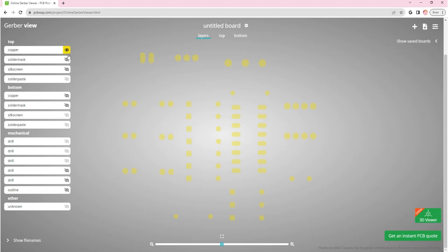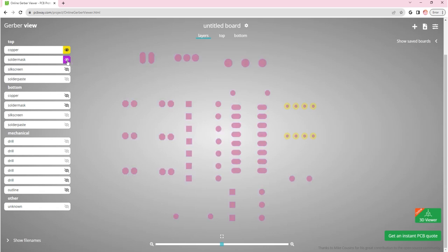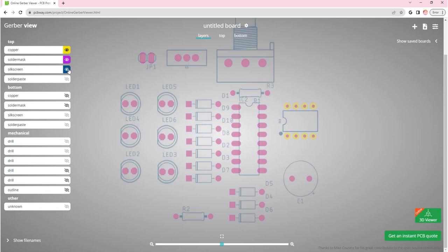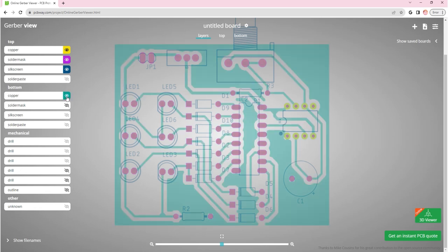The PCB manufacturer requires specific information pertaining to each step in the manufacturing process of your board. This special information is described in files containing plot and/or drilling information. For example, one file for each signal layer, for the silk screen, for the solder stop mask, the cream frame, for a gold application, for a glue mask, or for milling data regarding cutouts in the board.